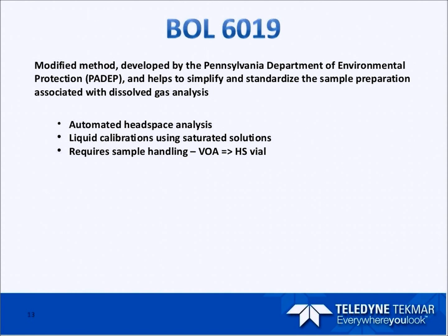And it does still require sample handling. You do have to take the water from the VOA vial and put it into a headspace vial, but really that's the only sample handling you have. It has calibration requirements, which the SOP RSK175 does not really have. They have set a percent RSD of less than 20%, or an R squared value of greater than 0.995. Those aren't too difficult to get. Calibrations seem to hold pretty well, so not usually too stringent of requirements on this analysis.